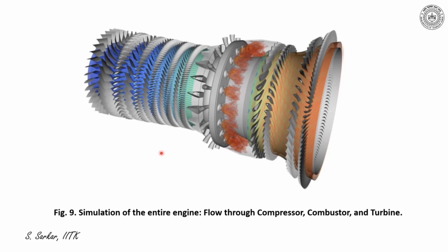Same results of the entire engine simulation, but in three-dimensional views are presented here, where you can appreciate the small scale eddies resolved in the combustion chamber. With this, I'd like to say that even though different components have been simulated together, considering a massive simulation, the resolution of flow is considerably good.